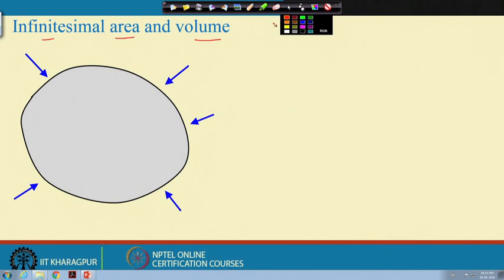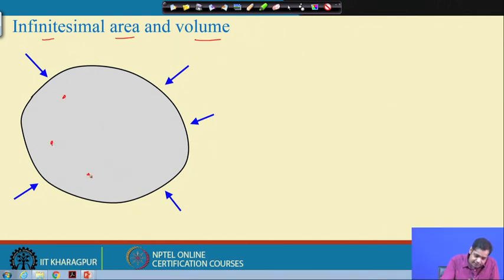because stress is a point-wise description. If we take several points in the same object, then the stress at different points is not the same, it may be different. So, we cannot say what is the stress in the body, rather we have to ask what is the stress at a given point in the body. So, stress is a point-wise description. When we say what is the stress, implicitly it means what is the stress at a given point.